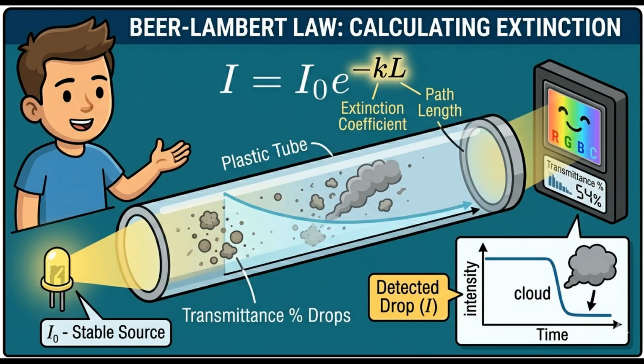Then you have the sensor, and I'm using a TCS34725 and an OPT4048 as light sensors. I also treat my LED very carefully in the electrical supply. I limit the current and expect that light source to be the same intensity and color every time I look at it. When you use a transmissometer, you'll get changes over time, and you need to keep a clock going so that you can measure the changes over time.